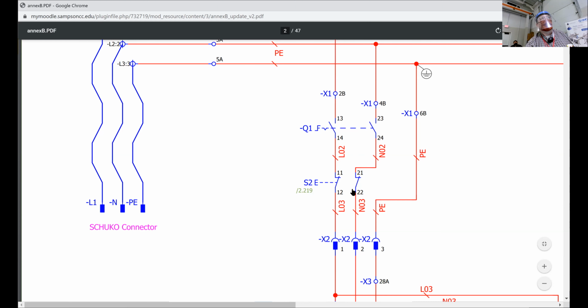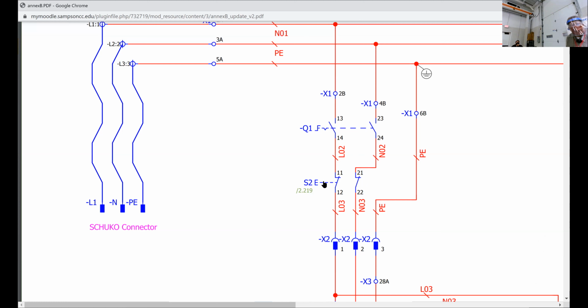This is the IEC symbol for a normally closed contact. If you notice here, the international schematics draw stuff that runs up and down. They don't draw it left and right like we do up here. Their ladders are laying down, and the power goes from the top, top down, not left right. So if it comes from Europe, Japan, somewhere like that, instead of their ladders standing up with the rungs this way, their ladders are laying down, and the rungs are like this. You get the idea? It's like taking a ladder and laying it down, and the rungs are vertical. That's the way the international schematics are done.